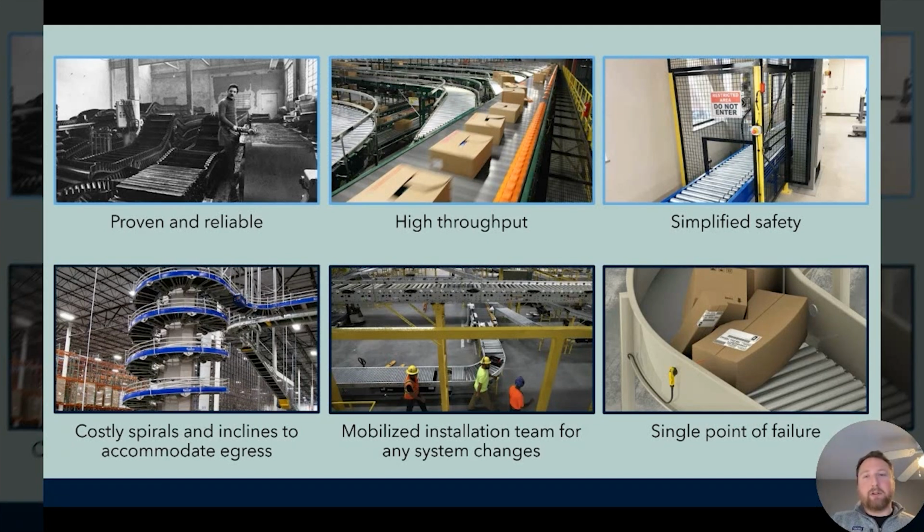There's also really no comparison when we're talking smaller scale movement that conveyor will basically always be the highest throughput option, whether that's just sorting or transportation. Conveyor being fixed there, being able to run 200, 300 feet per minute is an option that most AMRs and AGVs can't compete with.